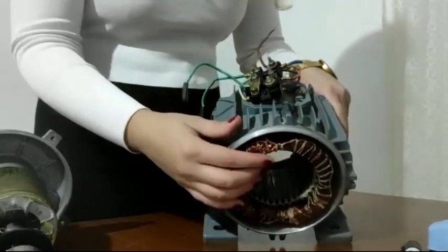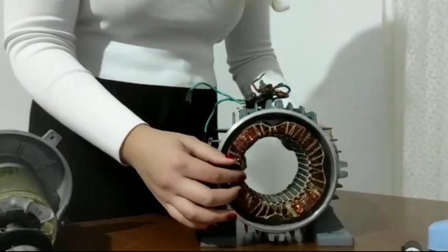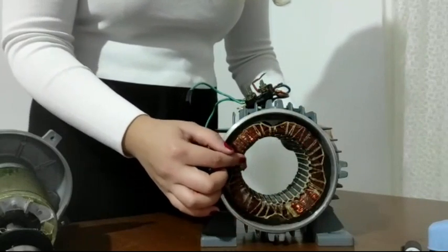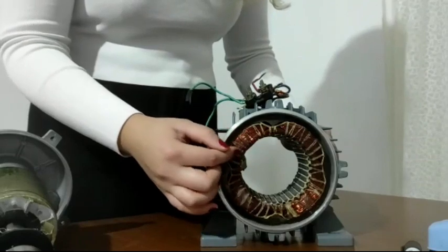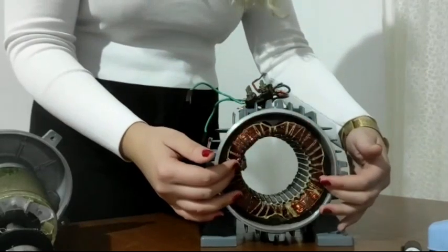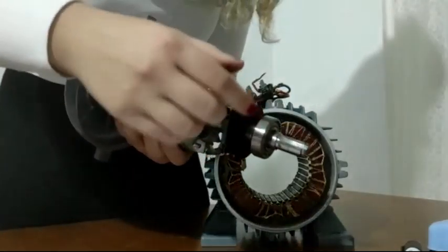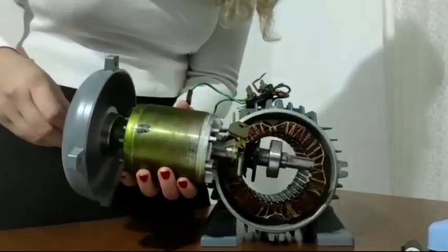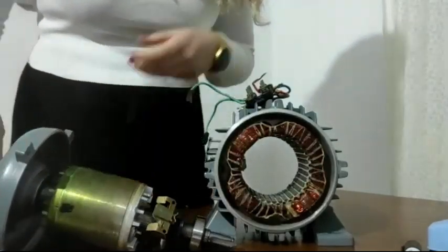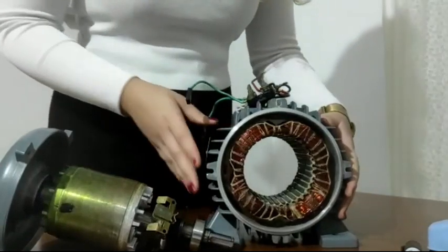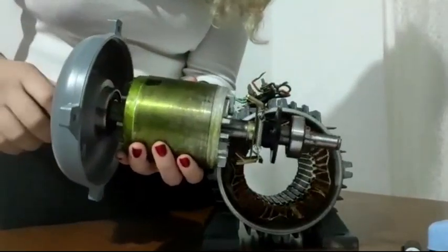As I showed you, the stator is a fixed structure and is connected to a three-phase supply. Basically, it's a three-phase coil winding, and three-phase alternating current is applied to the windings. It passes through these grooves, which you can see right here. They are made of thin steel plates, inside an outer structure made of steel or cast iron, like you can see here.